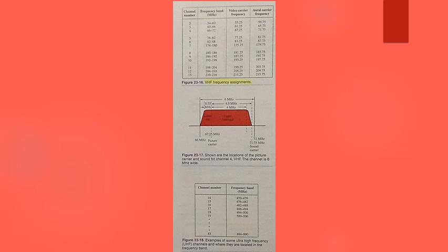The basic video carrier frequency is 67.25 MHz. Recall that when an RF carrier wave is amplitude modulated, sideband frequencies appear. These stand for the sum and difference between the carrier frequency and the modulating frequencies. To send a very clear, sharp picture, frequencies of at least 4 MHz are needed for modulation.